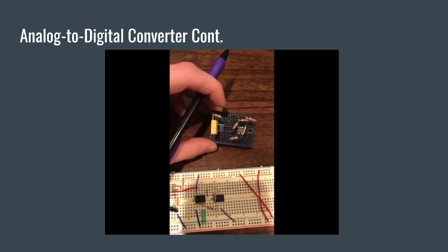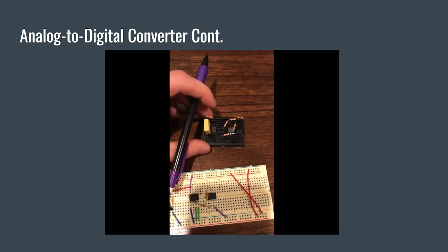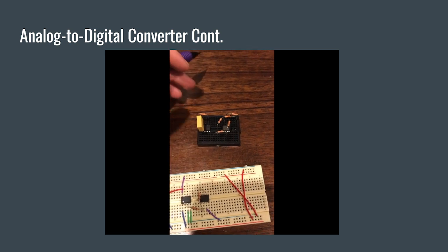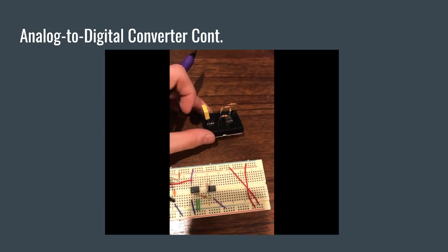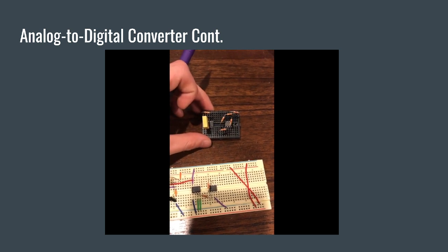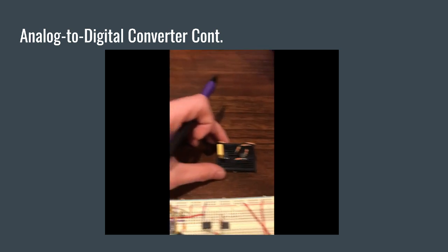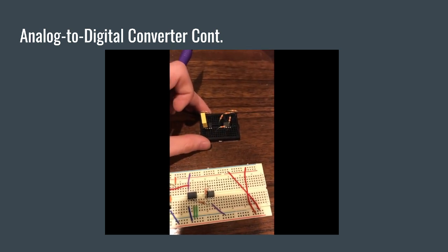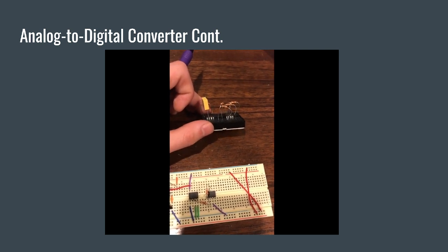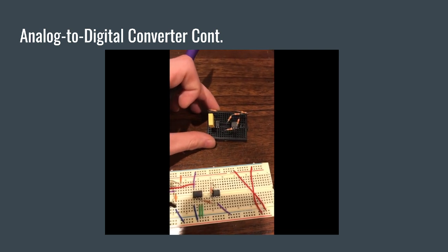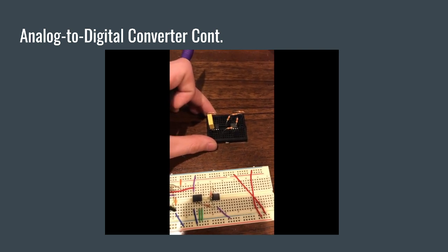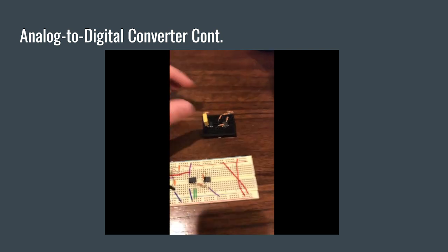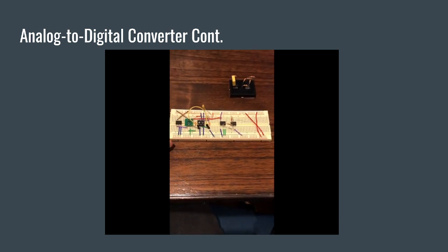The components are acting erratically, so we are getting extreme oscillations as our outputs, as well as our op amps not behaving well. We think it's the bypass or decoupling for the capacitors, so we are switching them out and buying new parts, hopefully before the final demonstration, and we'll be getting this all sorted out, as well as finishing our testing for the main ADC.